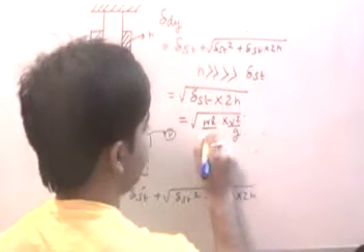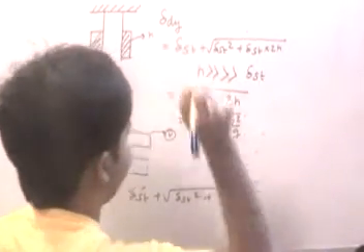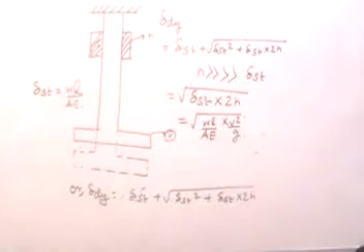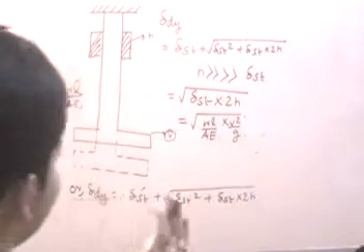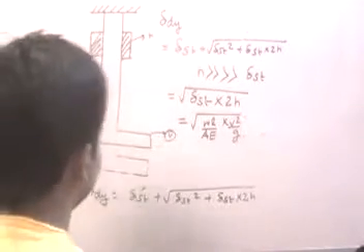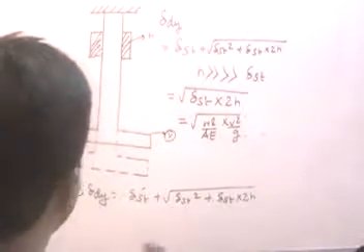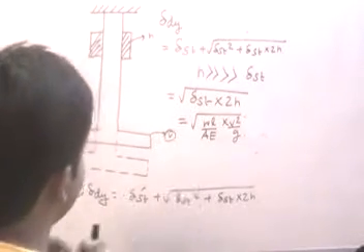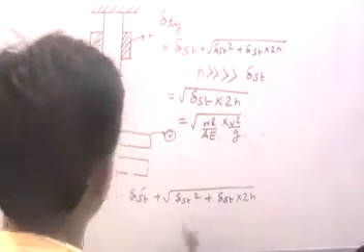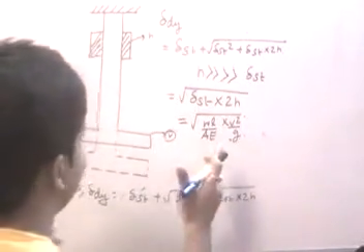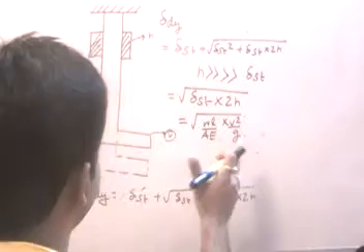as again WL by, let's say, AE. So the deflection due to dynamic loading is definitely dependent on this velocity factor, right? In case of static loading, the deflection was not dependent on the velocity factor, as there was no velocity at all at the point of impact. So deflection here will be definitely governed by kinetic energy.